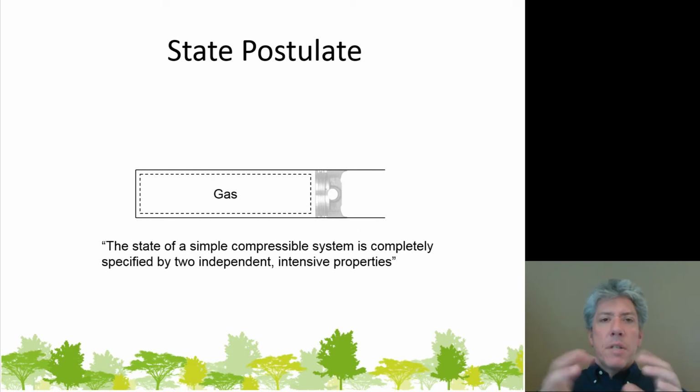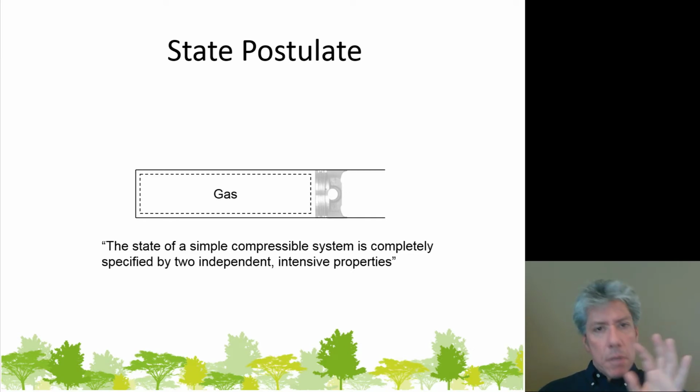But think about it. If I just have a simple piston cylinder device with air above the piston, so it's a simple compressible system, well, if I know the pressure and temperature of the air, wait a second, PV equals mRT, if I know how much mass is in the system, I can say how much volume there is, right, from the ideal gas law. Now you can say, well, isn't mass another property of the system? In a sense it is, but I'll show this to you later again, but if you take that mass and divide the volume by the mass, guess what you've got? You've got specific volume. So we'll actually use the ideal gas law in the form P multiplied by lowercase v, which is the ratio of the volume to mass, equals RT. We'll use it where all of the variables, the pressure, the volume, and the temperature, are intensive properties. Okay? And so it'll turn out that if you have two independent intensive properties, like pressure and specific volume, or temperature and pressure, you can calculate the other one.